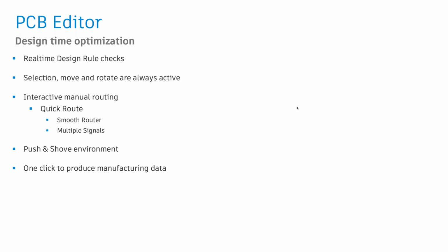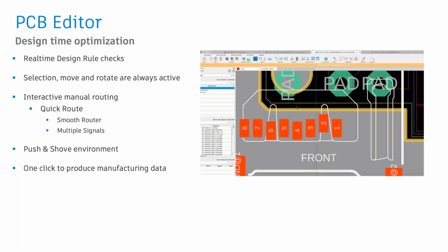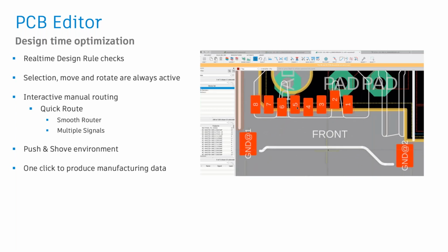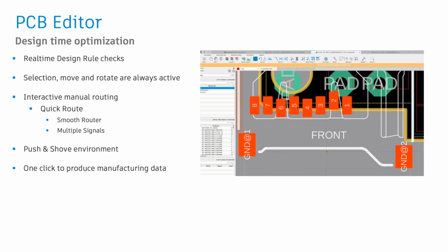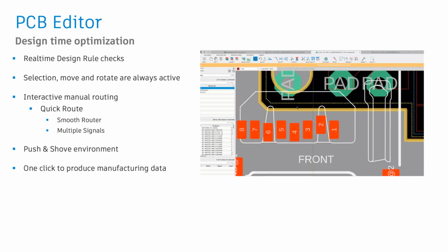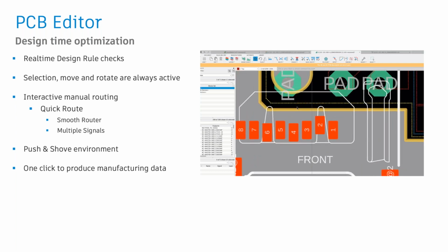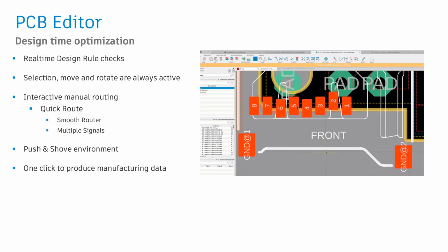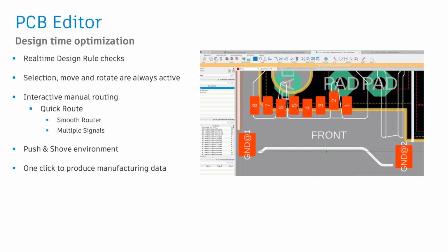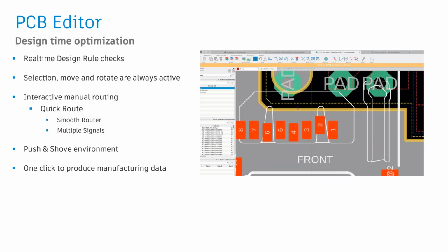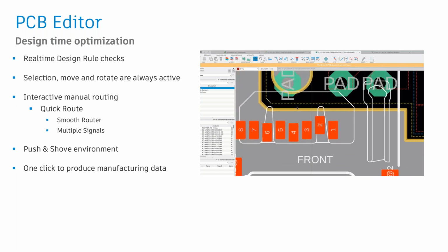In other words, first step, real-time design rule checking. As you see on my GIF file here, you'll notice that you get these hatch lines where there are violations. Commonly, in other applications, you have to place the components, then run the checker to see what errors you have. With Fusion 360, you get that identified immediately. Therefore, you know that you're in violation, not having to then run two commands to find out what your violation is. You are getting them in real time.